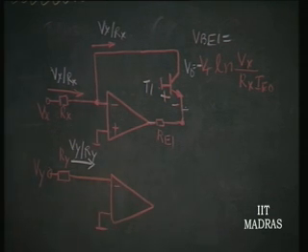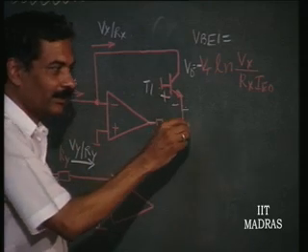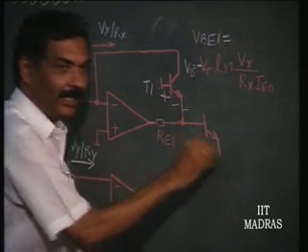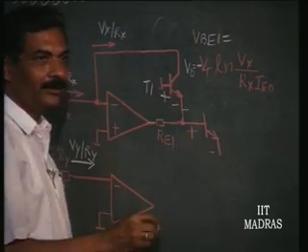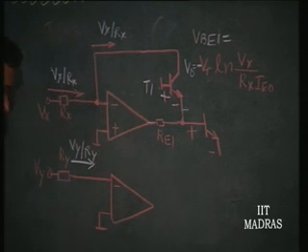and that again has to be converted into a log voltage. Adding requires, you might think, another amplifier. It does not require, because we have a voltage here, we have to put in series with this another voltage, which will correspond to the same thing, but determined by this current.